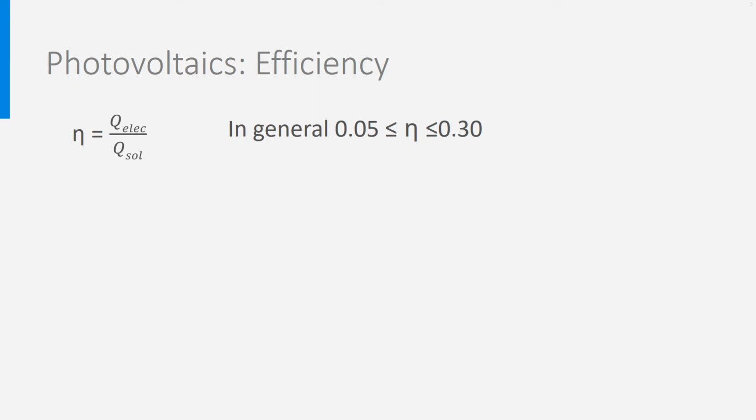That is around 23%. This determines a theoretical maximum efficiency, although there are developments to make more use of the whole spectrum by using several layers of conductors, each with a specific absorption spectrum, making the efficiency increase to almost 30%. In total, there are even more losses, as many of the photons are just lost in the material and do not hit an electron, and there are also losses in the electrical circuit and junctions.